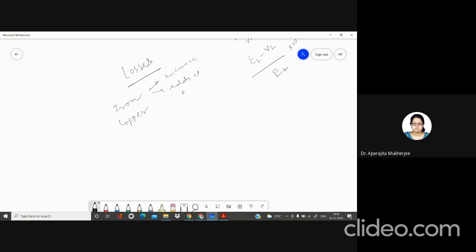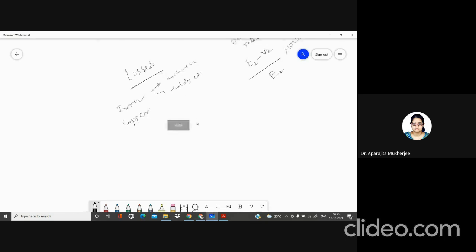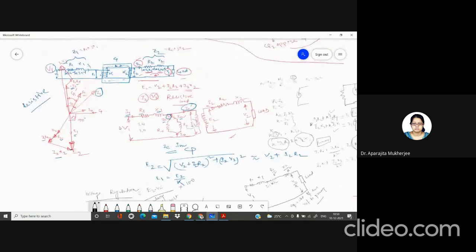If the magnetic circuit is made up of iron and the flux in the circuit is variable, currents will be induced by induction in the iron circuit, and these currents are known as eddy currents. Eddy currents result in loss of power, with consequent heating of the material. We know the two expressions for hysteresis loss and eddy current loss.